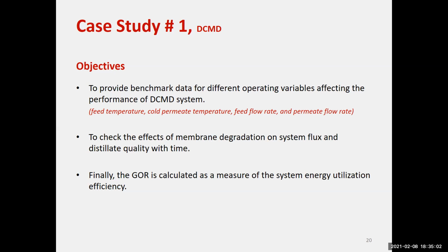So we needed to see the effect of these parameters, which of them are more significant, so that if you are going to build a system, you know what parameter you should worry about. Should I worry about increasing the flow rate more, or should I worry about the temperature more? High temperature or low temperature? Is it enough to use room water temperature for condensation of the vapor, or do I have to cool it down using a refrigeration system or a cooler? What's the problem with that?